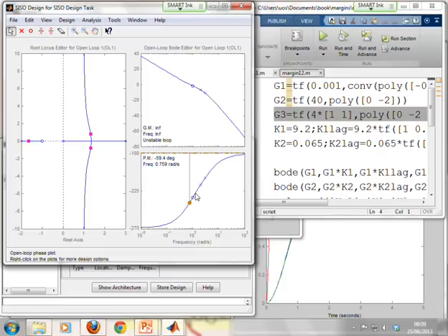And you know that a positive phase margin means this brown line has to be above minus 180 degrees, whereas currently it's below. But you know that the phase lead can lift you by up to 55 degrees. Now at the moment we've got a phase margin of minus 59, so if I lift that by 55, it's still going to be negative. So I can't choose this gain crossover frequency because I can't get enough lift from the lead. So I've got to move this brown line over here to the right before I can actually create a positive phase margin with the lead.